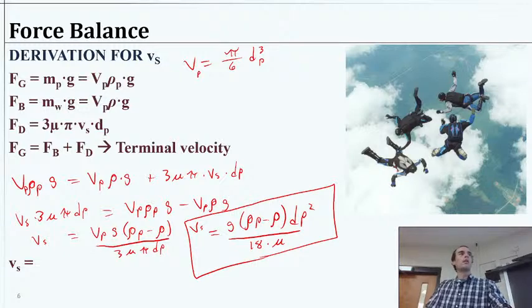We can actually do artificial changes in gravity by centrifuging things, causing particles to sink faster. We use that a fair amount in a lab. You're just essentially inducing an artificial gravity, causing sedimentation. You can change the density, perhaps, of the water just a little bit by changing the temperature. So if you're doing sedimentation during the winter versus the summer, that might actually be a little bit important. You could also maybe change the density of the particle. But none of those changes are really going to make as big of an impact as changing the size of that particle. So the larger the particle, the faster it will sediment.